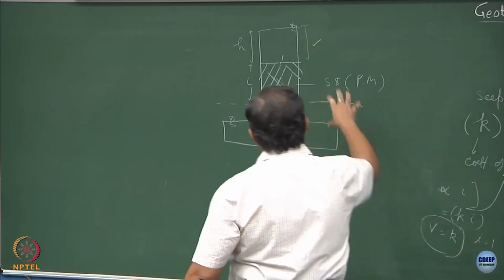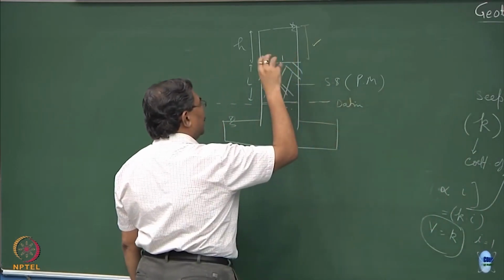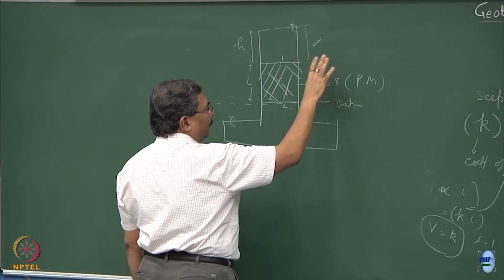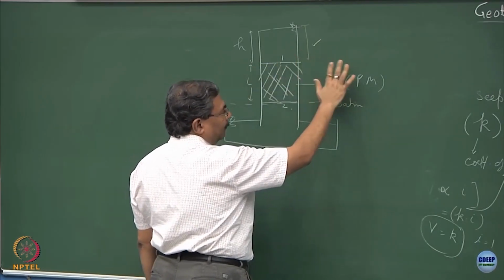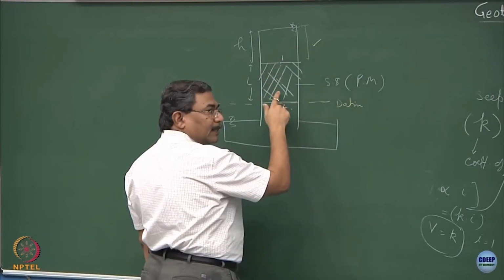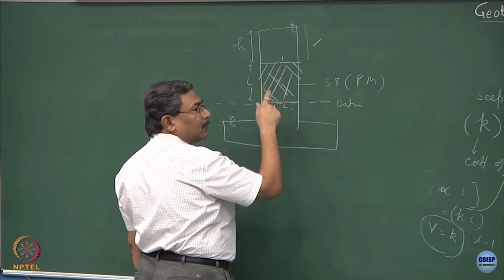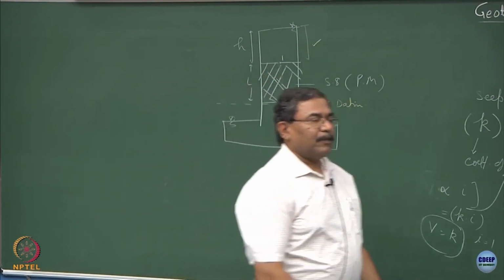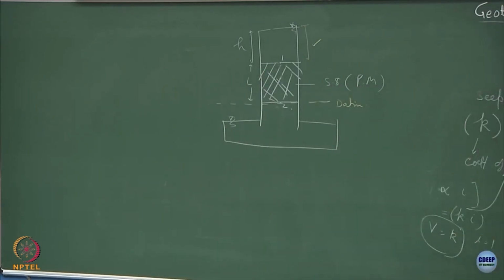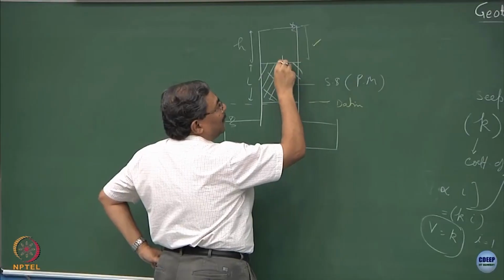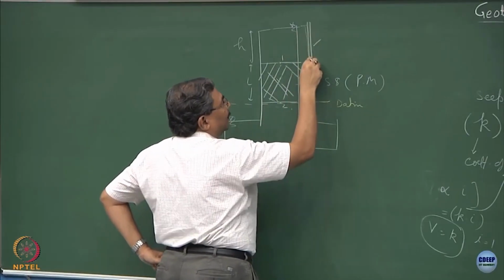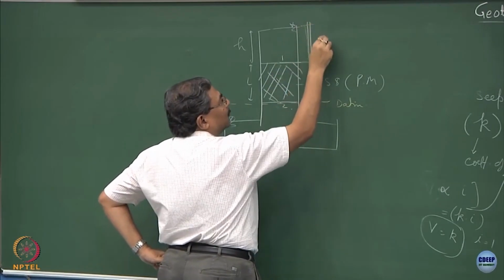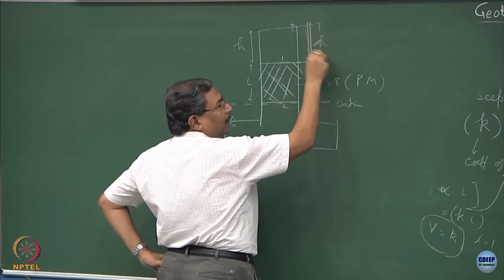By virtue of being a porous media, the void ratio, density, soil property, specific gravity all are defined. What you are ensuring is this is a steady state and hence the sample is fully saturated. If sample is not saturated, then the problems will occur. We always talk in terms of meters of the pressure head. If you remember, the pressure head at this point is the height of the piezometric rise in water. So, this is going to be H, clear.